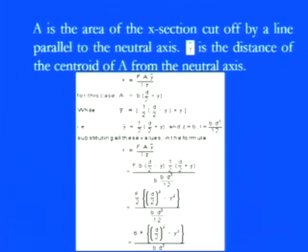Now, keeping those parameters in mind, we want to put them into our first formula, that is, shearing stress is equal to F into A into y bar divided by I into Z. So now if we substitute, in place of F we have the shear force, which is pretty common, and then we have the area.